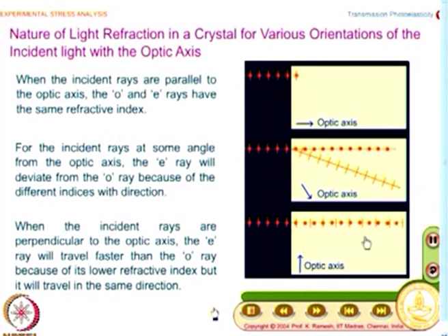The phase retardation is not because of depth change, it is because of the way the material behaves like a crystal. Crystal behavior is perceived as N1 and N2 at the point of interest, and this N1 and N2 could be related to what? Sigma 1 and sigma 2.